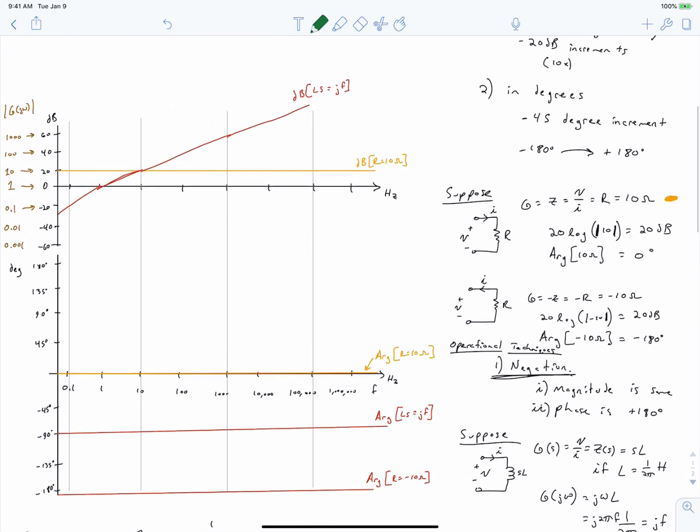And we can do this by going back to our Bode plot and now reflecting our magnitude plot about the axis, taking the negative of it, which is going to look like this. And so this was decibels of 1 over LS. And similarly, we can go to our phase angle plot and see that we're just going to have a straight line going across.